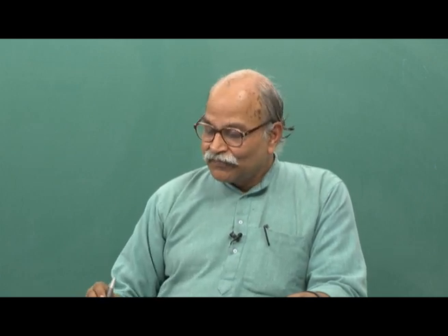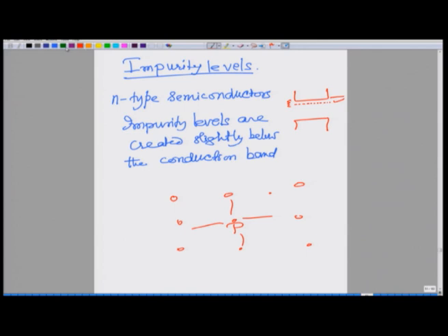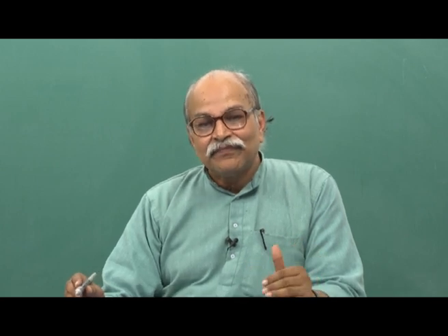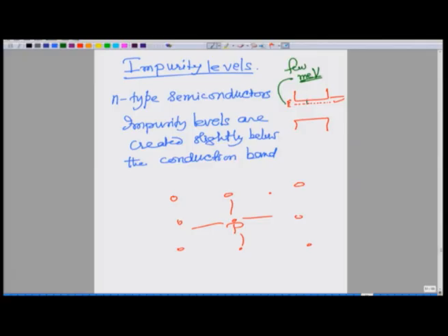So, that is how this impurity level that we were talking about is generated at say 10, 20 type milli electron volts of energy, which is comparable to kT, Boltzmann constant times absolute temperature, and that is why it is very easy for these electrons to go and populate these conduction levels.